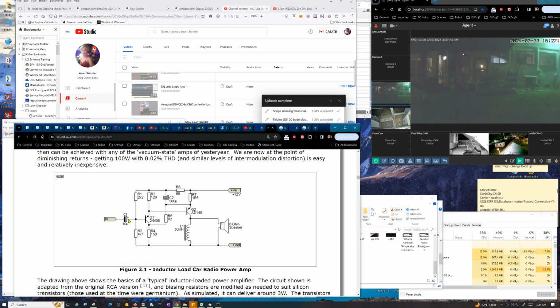But like I said, even here, obviously given the polarity, he's got a voltage divider driving this transistor, and basically you can see that's actually a relatively high voltage. It's got 4.7K versus 2.2K, so that means the voltage is going to be somewhere in between VE and ground, right?